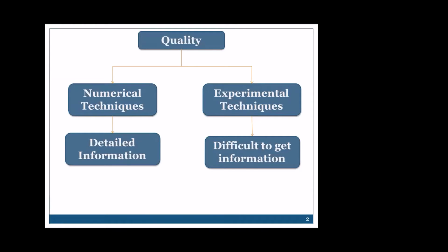So in order to get homogeneous casting products, it's necessary to know and control all the physical phenomena involved in the process, as heat transfer, solidification, fluid flows, and also thermomechanical processes with the process parameters as cooling rates, inlet velocities, and the casting temperature. However, it's very difficult to improve these processes using experimental techniques because it's difficult to measure velocities, temperature during this filling. Therefore, numerical simulation is commonly used because they provide a large amount of information that cannot be obtained with other kind of methods.